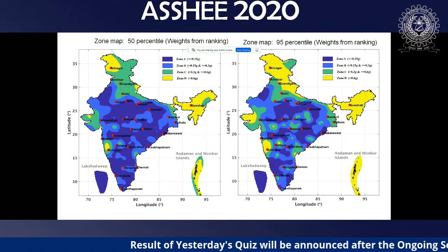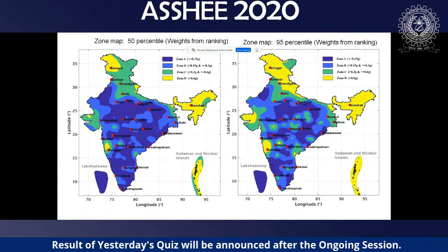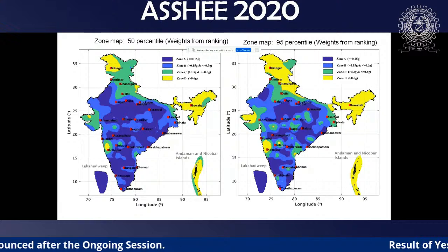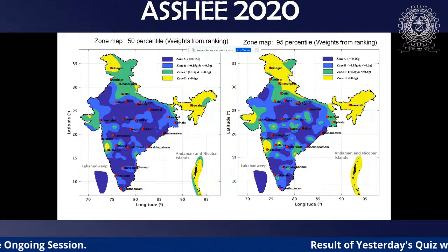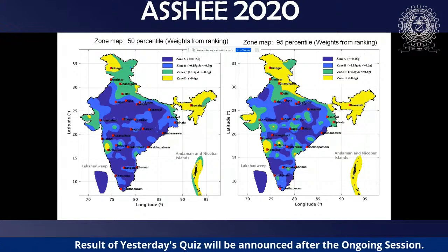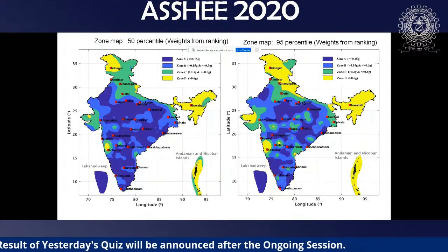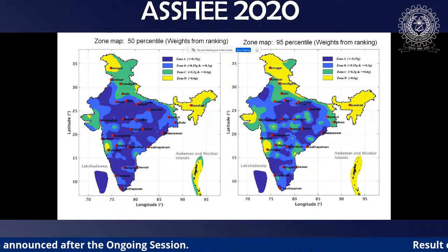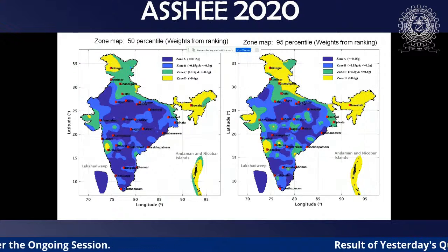And now, in India, we can give these hazard contours for 73 year, 475 year, 2475 year. But our practicing engineers are accustomed to our zones itself. So if I give a variety of these contour maps, it will be very difficult for them to understand. So what the committee felt was, we will go ahead with these zones itself.